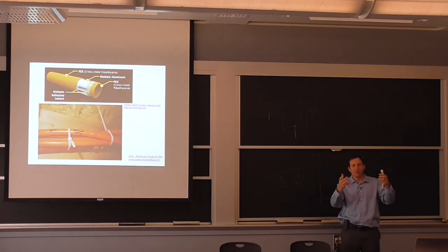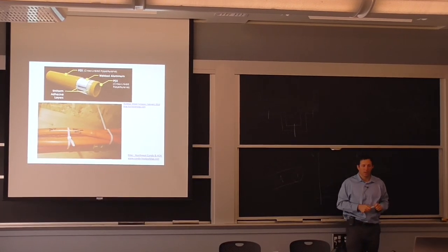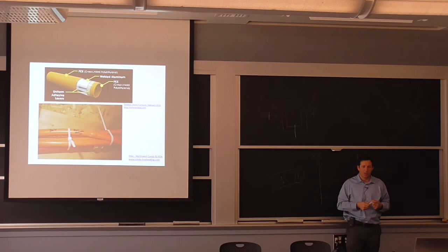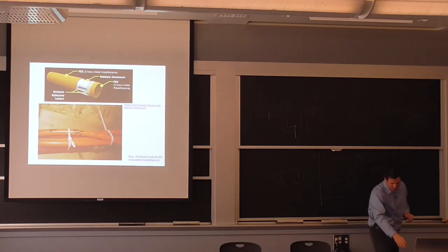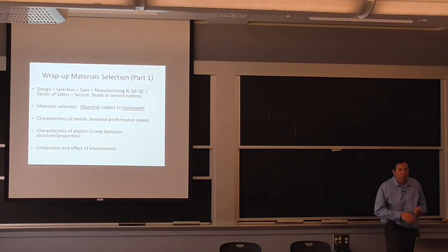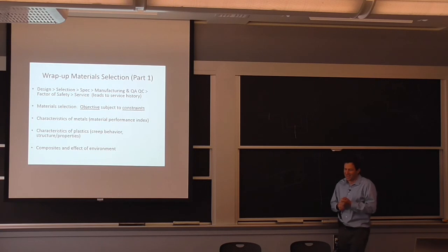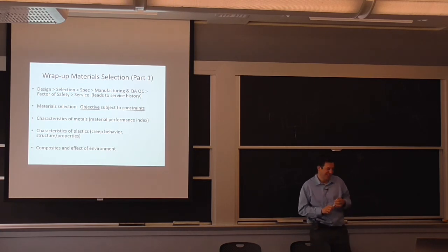So it's a lot easier to lay out your plumbing system. You don't need as much fitting. So people really liked it, but it wasn't built for those specifications where you have more oxygen than in a radiant system. And Kitec paid $250 million in lawsuit damages in Las Vegas alone.